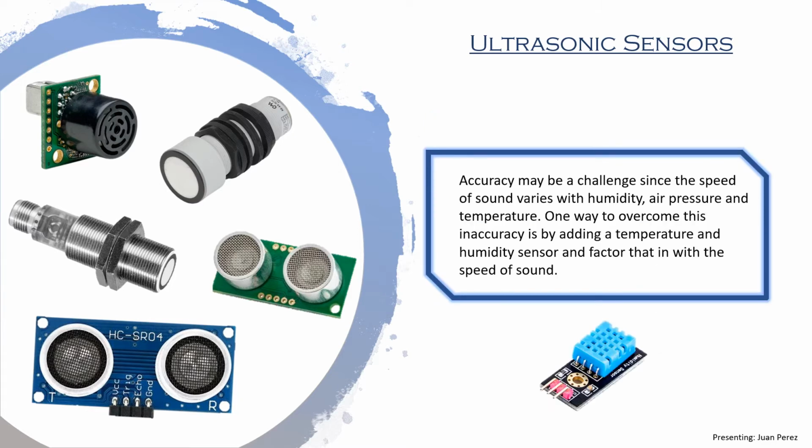Accuracy may be a challenge since the speed of sound varies with humidity, air pressure, and temperature. One way to overcome this inaccuracy is by adding a temperature and humidity sensor and factor that in with the speed of sound.